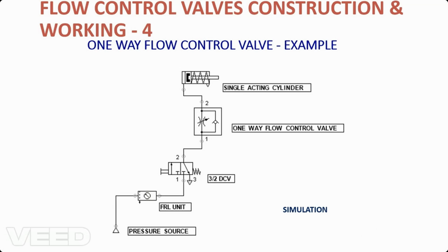A simple application where we use this is stamping. In the F&B industries we have printed labels. For that printed label, depending upon the product, the pressing needs to be slower. For that purpose, we use this one-way flow control valve.